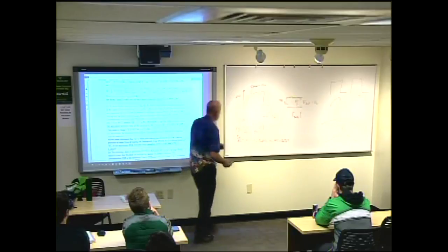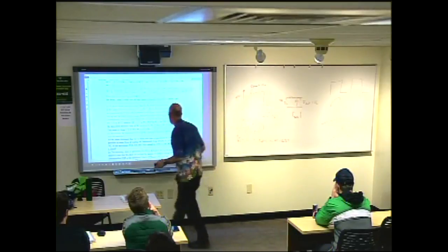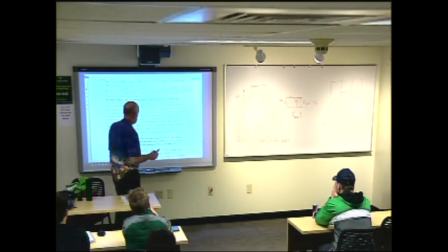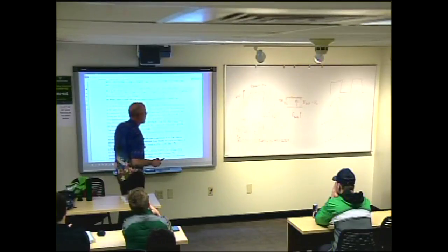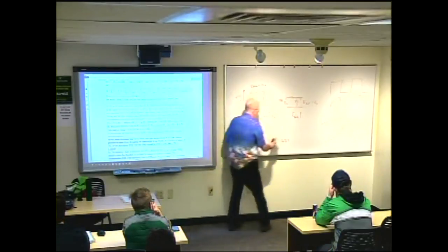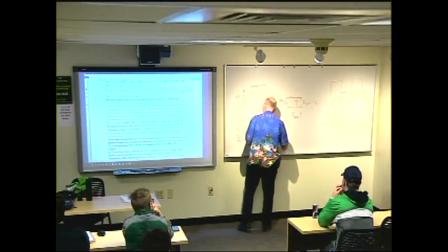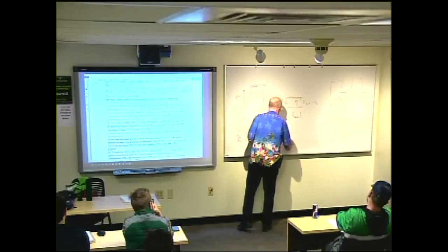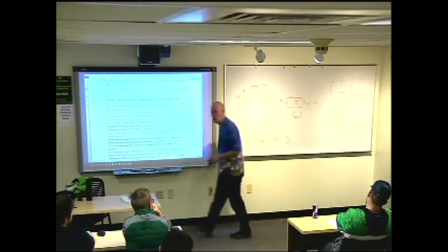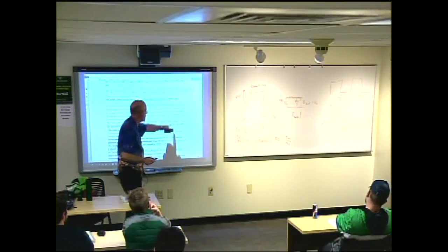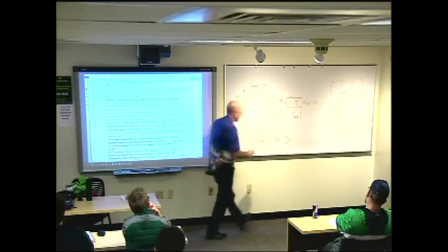Oh, I'm sorry, these are not seconds. Let me carefully work through this. Yeah, I messed it up. It's not RC equals 202, it's RC equals tau n over 101. That's what it is. So if I plug in 2 seconds divided by 101, I get about 0.02 seconds